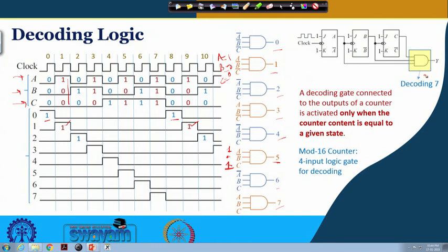So, in the circuit, in this place instead of a 3 input AND gate, we shall put one of these connections, and wherever A bar is needed, we have to take it from the inverted output instead of A, the way it has been shown here.